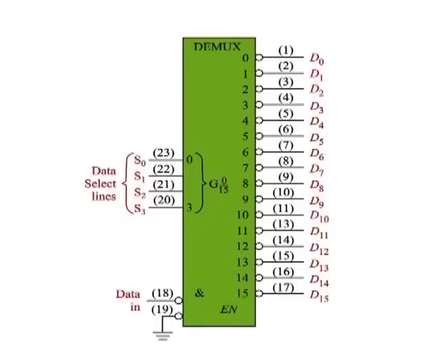In demultiplexer applications, the input lines are used as the data select lines. One of the chip select inputs is used as a data input line, with the other chip select input held low to enable the internal negative AND gate. This device may be available in other CMOS or TTL families.